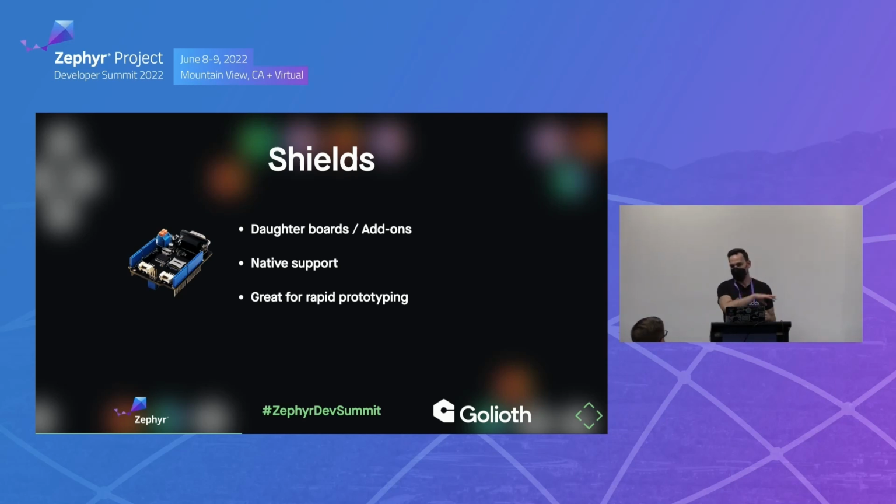And so out of the box, there's a couple dozen shields already. You can even make your own shields. So as you're going through that R&D process, taking your sensors, maybe you have some power system, design a shield, manufacture it, and now your teammates can have a reusable shield component and not have to worry about, let's say, application code and sort of the sensing code. It's really useful for rapid prototyping. We see companies actually grab a shield from Amazon, use it to bring up their Zephyr development, and then quickly design it out with the proper sensor or the proper network driver or whatever.